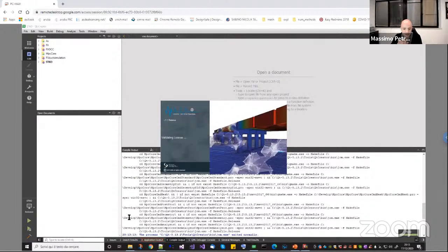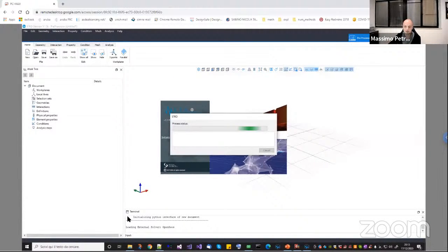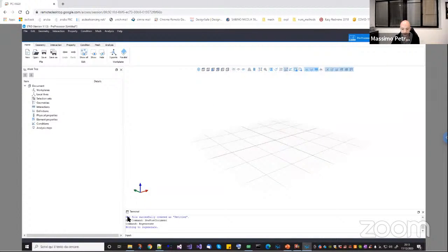It is a very flexible feature because in version 2, we implemented custom Python scripting for post-processing as well. So now basically the post-processor of STKO is like a MATLAB environment. You can do whatever you want with your results. And one of the applications can be, for example, the combinations of the results.